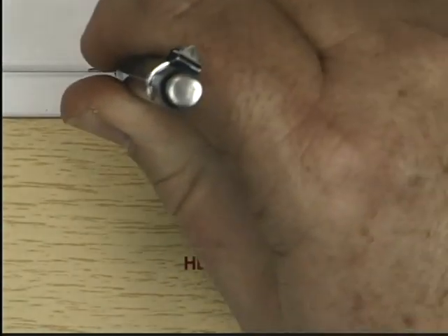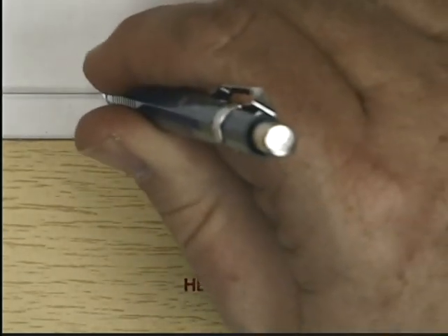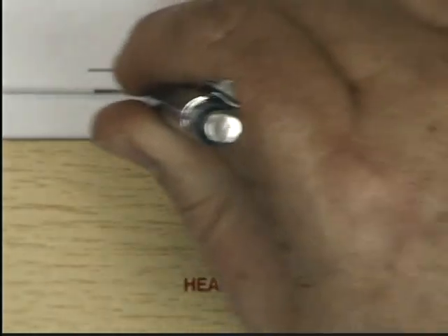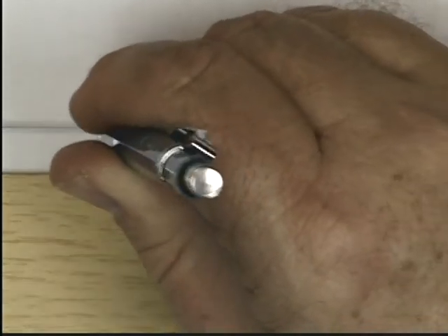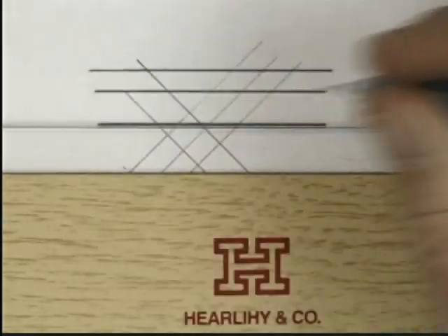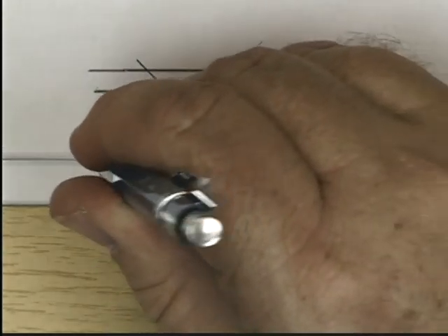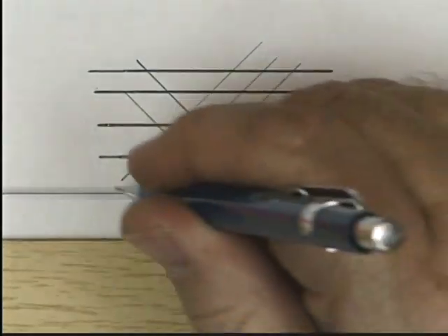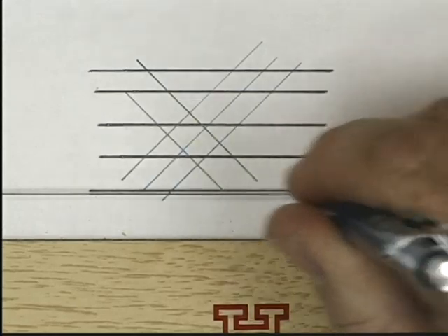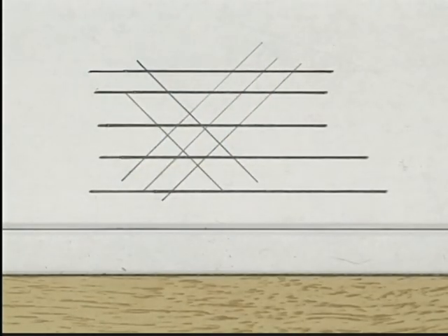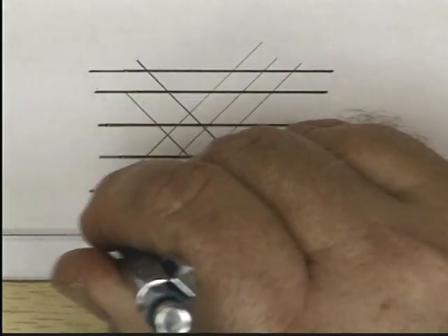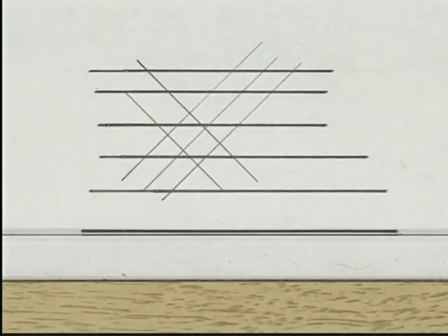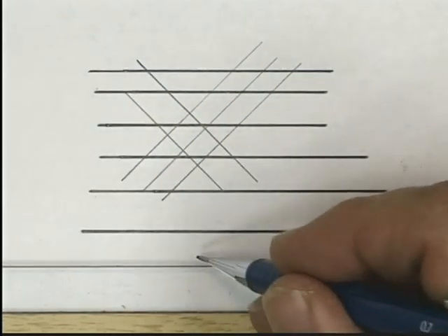I'm going to draw some dark lines, and I draw using the full width of that lead, and I use a lot of pressure for dark object lines. Now because this pencil has a nice 0.7 millimeter thickness, and because I'm using the full thickness of that lead, I never have to sharpen it, and I always get nice uniform lines. You might have noticed that I repeated. I went back and forth across there.